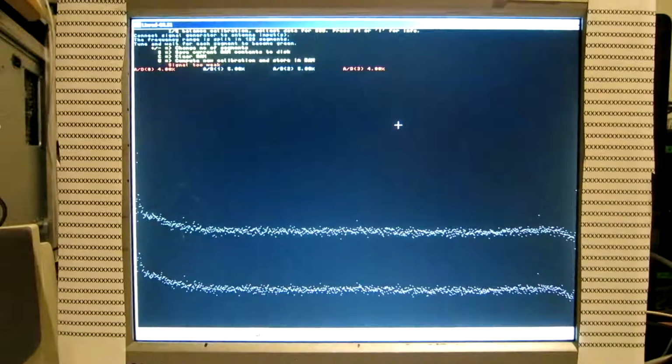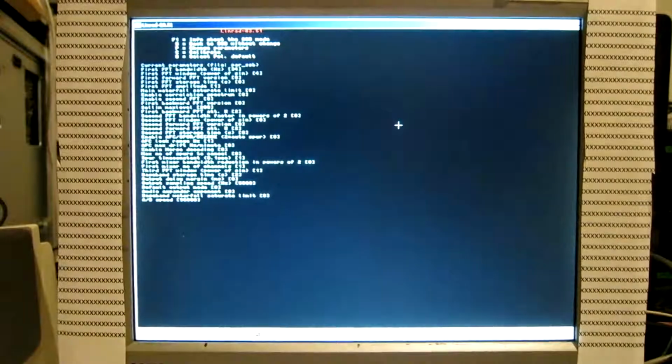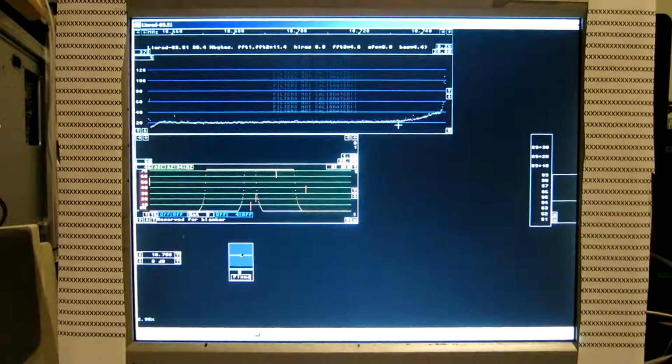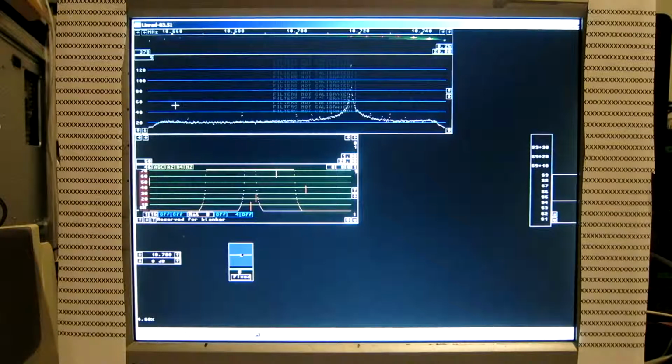So enter, save, exit X, and then back B. And have a look at the result. I make the frequency step 5 kilohertz and step the frequency. Now at the end of the spectrum we are here at 70 versus 130. That's about 70 dB. And a little bit closer, then we have better. It's 50 and 130. That's 80 dB, this level. And then it becomes better over the dominating range of frequencies.